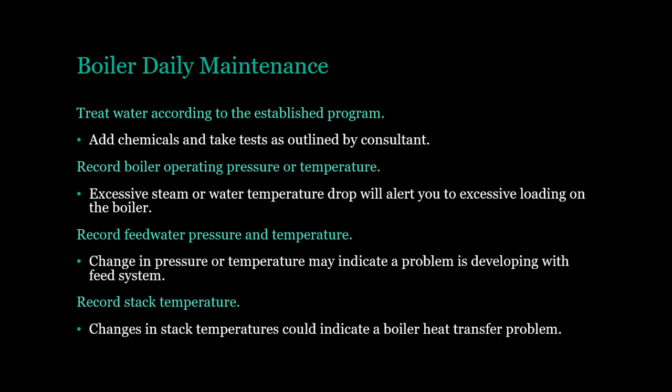Boiler daily maintenance. Treat water according to the established program. Add chemicals and take tests as outlined by consultant. Record boiler operating pressure or temperature. Excessive steam or water temperature drop will alert you to excessive loading on the boiler. Record feed water pressure and temperature. Change in pressure or temperature may indicate a problem is developing with the feed system. Record stack temperature. Changes in stack temperatures could indicate a boiler heat transfer problem.